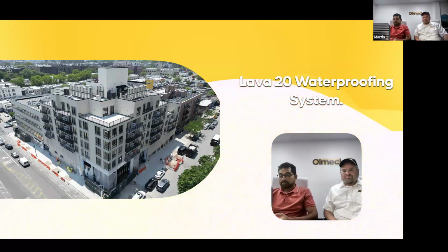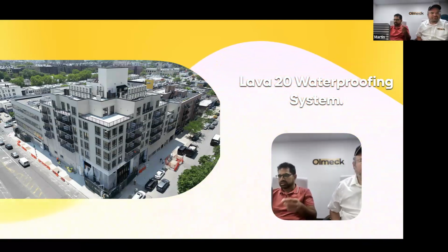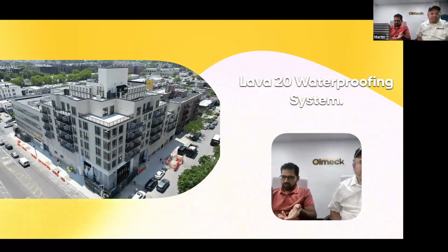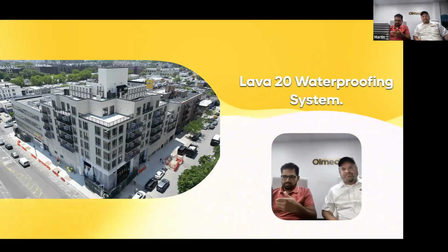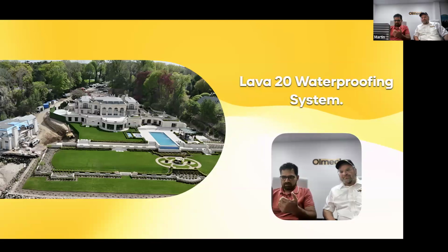We recommend using building code insulation, which is basically our R-30 insulation minimum for roofing systems for new construction. And then they could go with our liquid system, basically two coats with fleece reinforced in between, and that's the roofing system part.